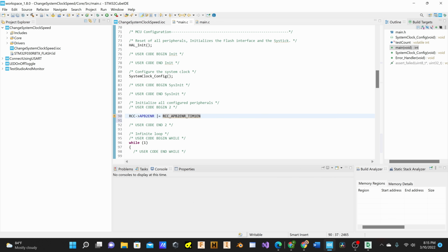Okay. And I got a comment stating that the way I'm showing how to set and reset bits, using this OR bitwise operation and the AND NOT bitwise operation, is a bit of a misnomer, because this is actually a mask. It's not really setting a particular bit number. And that is true, but there really isn't any need to understand bitwise operations and truth tables at this point. Just knowing how to set and reset bits is perfectly sufficient.